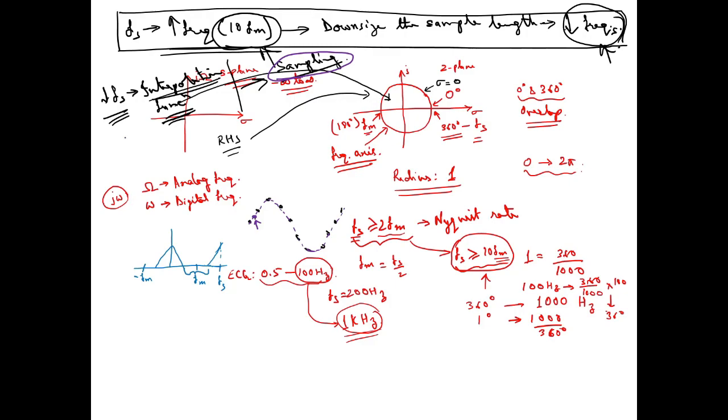But in the second case, you have to be very careful that the signal you are using should not be aliased. If the signal itself is aliased, that means the signal itself contains wrong information, and however much oversampling you do, if the original is corrupted, the final version of the signal will also give you corrupted information.